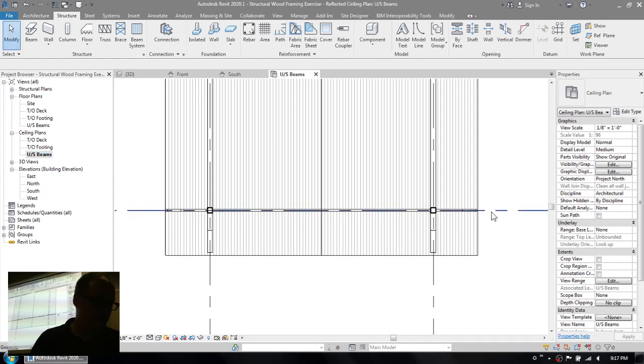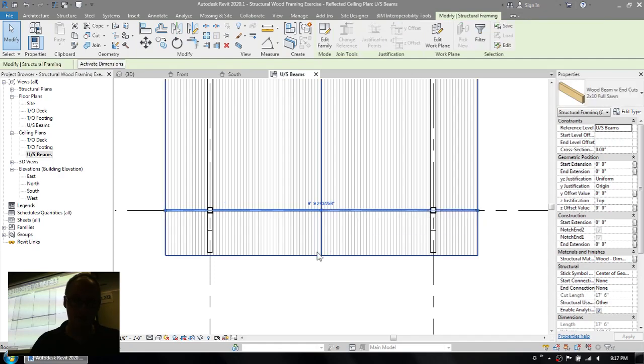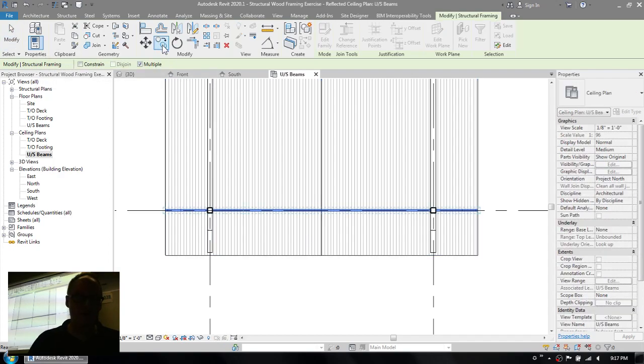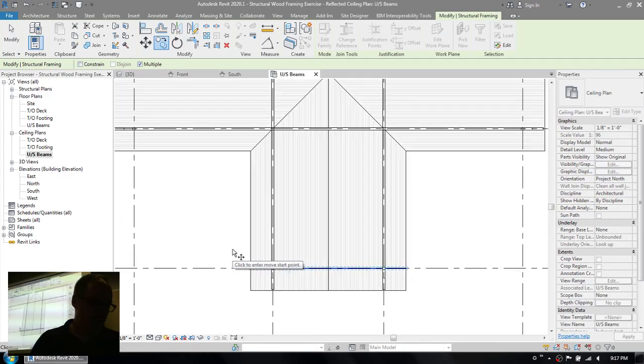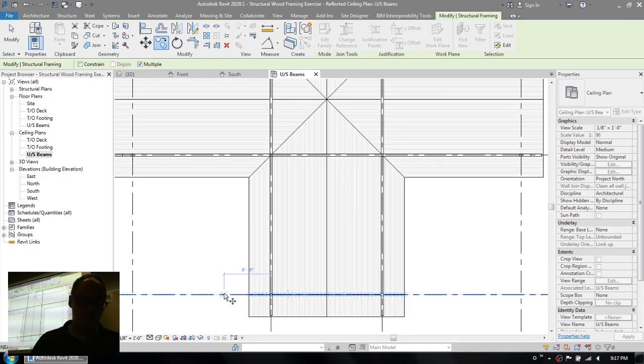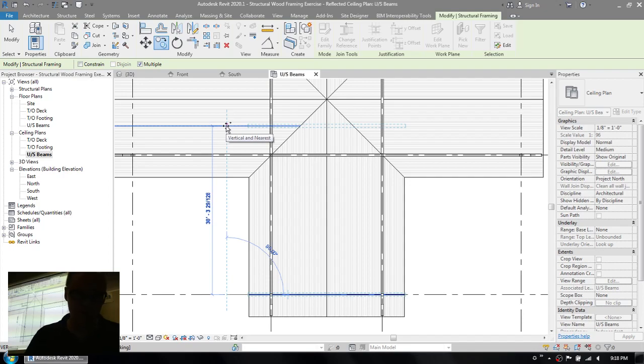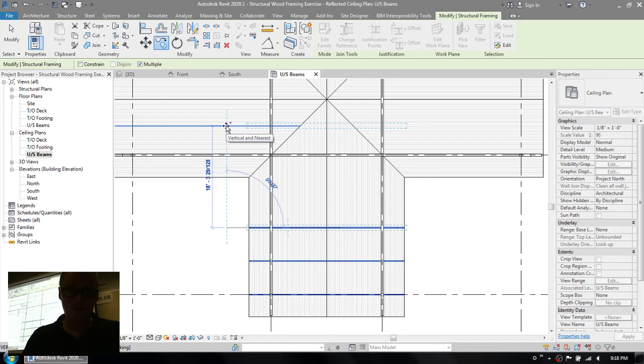Okay, at the bottom of the plan at grid D, you should see the beams you've just added. Select both beams, so hit the control key there, grab those two beams. And we're going to use the copy command. So again, we know what the joist spacing already is. So we need 5 copies, I guess total, I don't know. Click anywhere and then drag straight up on your screen, and we want 6-foot increments. So 6, enter, 6, enter.